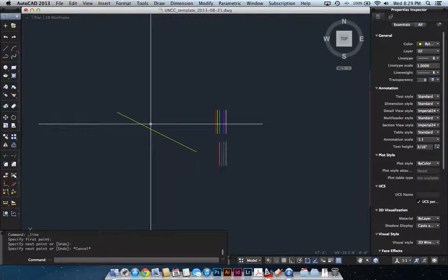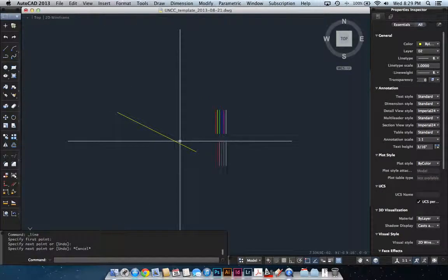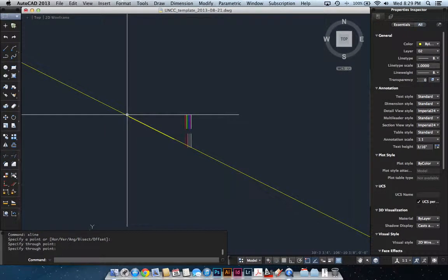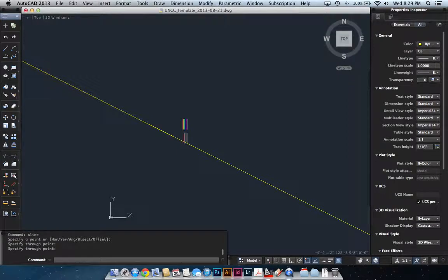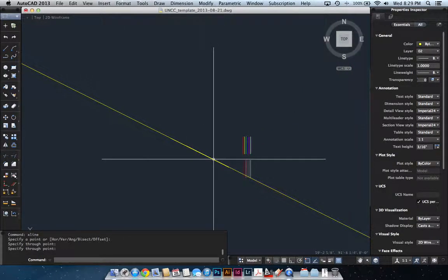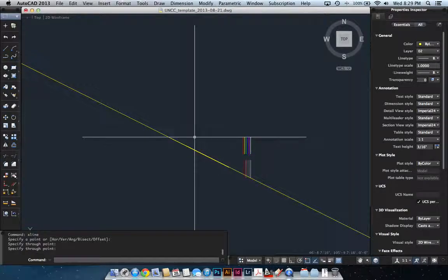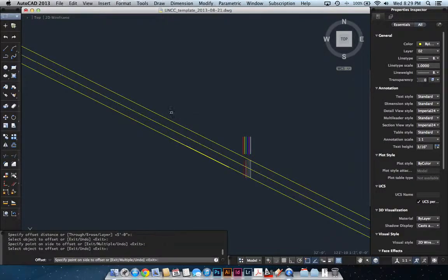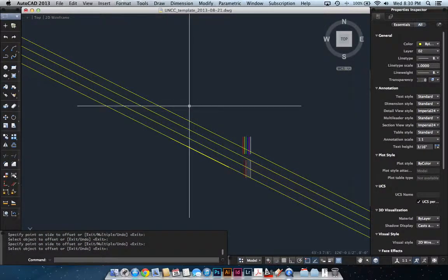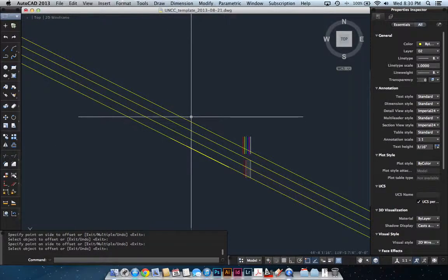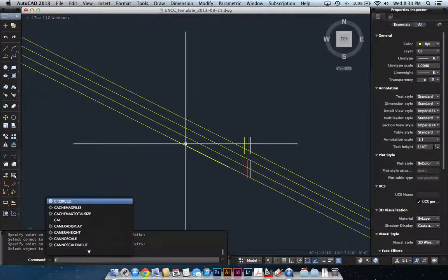But one of the things I can do is create an Xline, a construction line, along that angle, and now I can get this line infinitely as well in a coordinate plane. So again, it can be very helpful to locate particular pieces. I can now offset this 5 feet and so on. And as you can see, it now runs a set of ribs across that at the grain I want. And I can, of course, copy this.